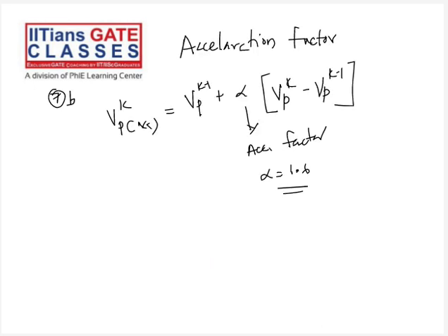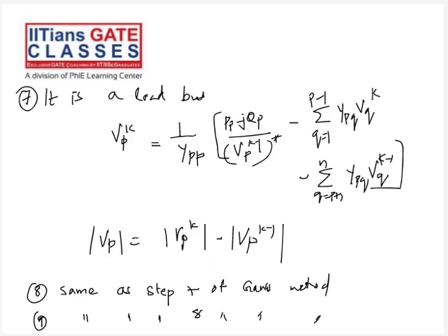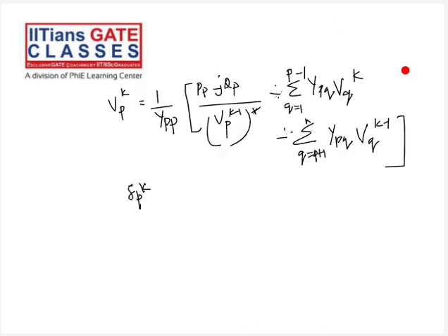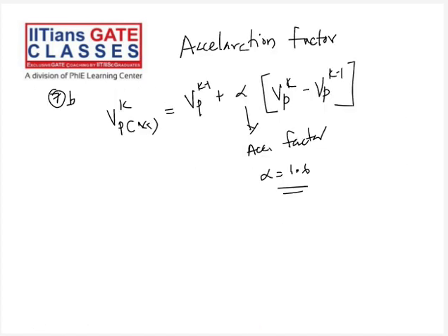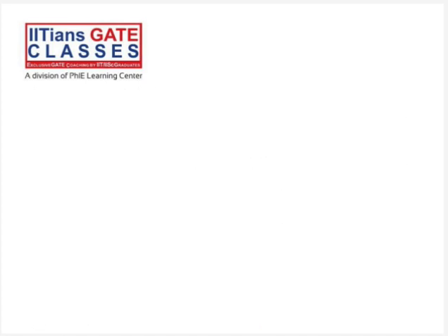Now see here, we improved upon certain conditions where we are treating load buses and generator buses separately. Then we are also using the latest updated values of system voltages, right? But there is also one more condition: here we are not putting any constraints on reactive power. But we saw earlier that reactive power of a generator is constrained, right?